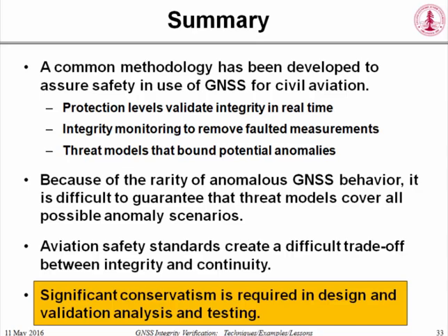Fortunately, GNSS, particularly GPS behavior, has relatively few anomalies. It's difficult to assure that the threat models cover all possible anomalies. So we have to be conservative in creating these threat models. The safety standards create, by definition, a difficult trade-off between integrity and continuity. And bottom line is, we are experts in conservatism. And also because we work in a consensus format, typically the most conservative, most pessimistic person tends to determine the amount of conservatism applied at the end.